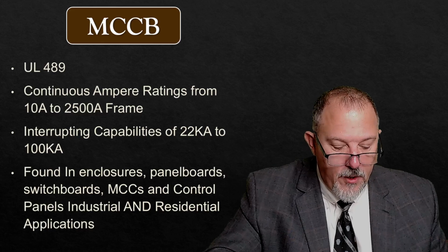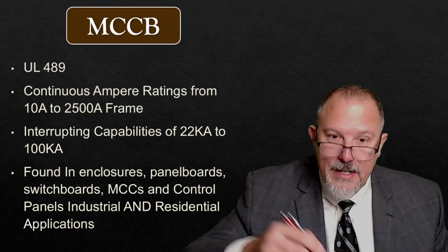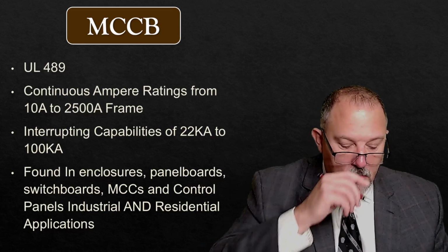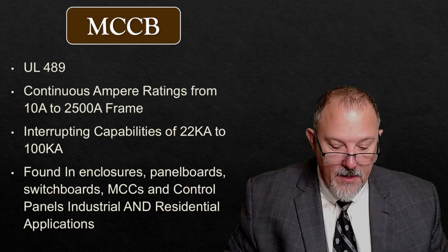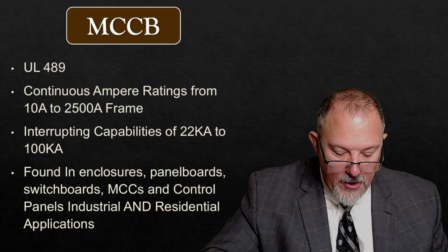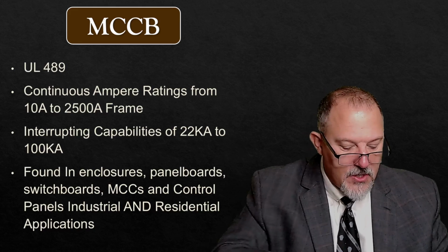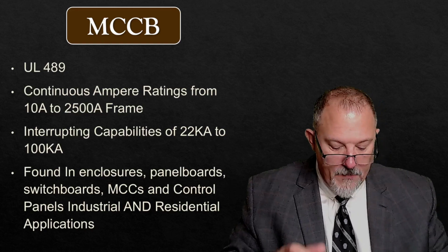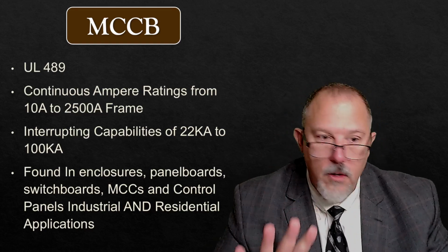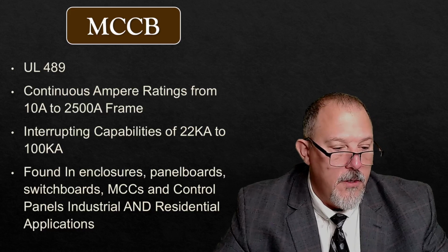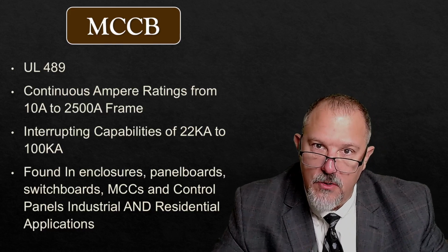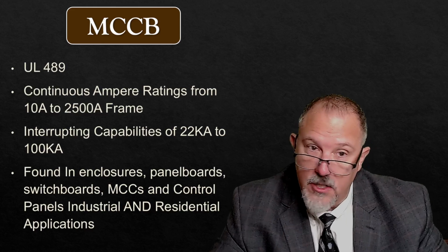And that's for 240 volts and below. Then there's 240 to 600 volts. And then the third one says 600 volt motor control center, fed from a 2-cycle device. You skip down to other 600 volt equipment, and there's the 2 cycles. Those are the only 4 locations in this table that reference a piece of equipment being fed from a 2-cycle clearing time device, which is a molded case circuit breaker.